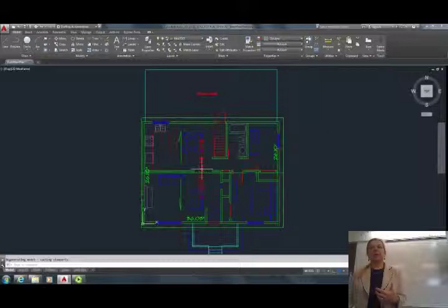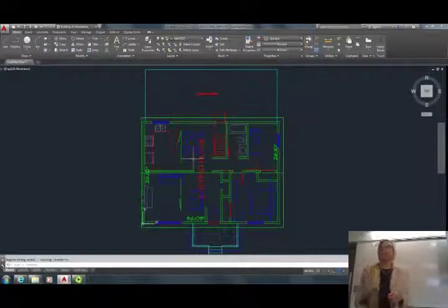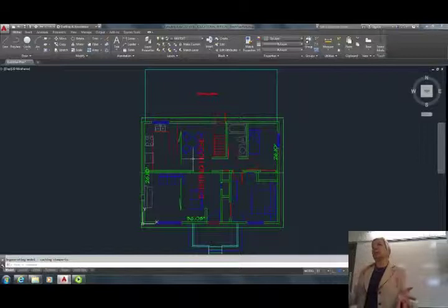It will also get blown up and it might be going beyond my walls and not be centered anymore and not look so good. So the advantage here is with annotative, all of your texts will change at the same time. With what I'm telling you, if you blow things up, they will also get all increased or decreased. But the individual texts are not going to be going up and down in value.